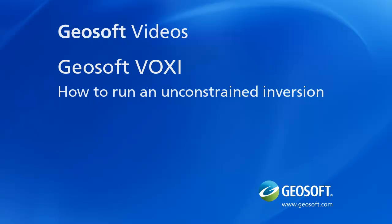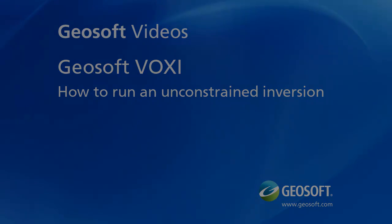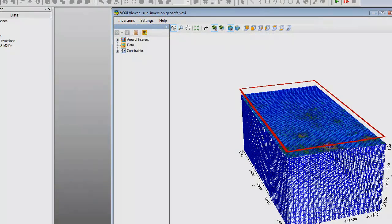and run an unconstrained inversion. This video continues from the steps covered in the previous Setting Up to Run an Inversion video available on the Geosoft website. In the previous video, we set up our inversion and made all the necessary adjustments to the parameters. Now we're ready to add more information to our model. We'll add the database containing the residual survey data and define some additional measurements and background removal options.